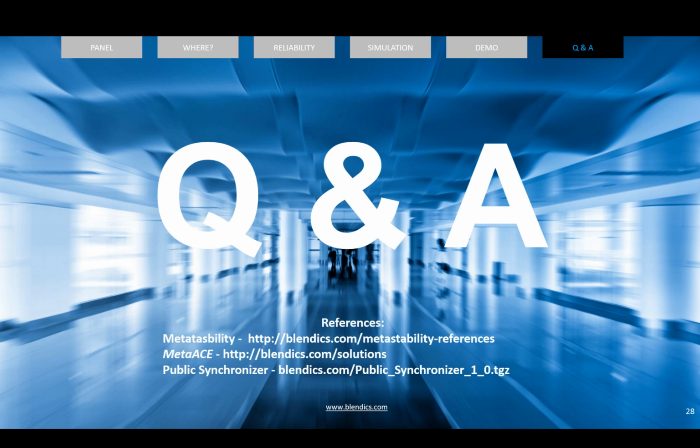We've done it ourselves. That's another parameter that you give the clock. When you specify what your clock is, you specify how many clocks to the output that you need. So the signal you're looking at is at the output of the third stage of a series of flip-flops, 3 clocks to the output. You'll get yourself a lot of coffee. But it'll give you a result of the performance of that circuit as well.